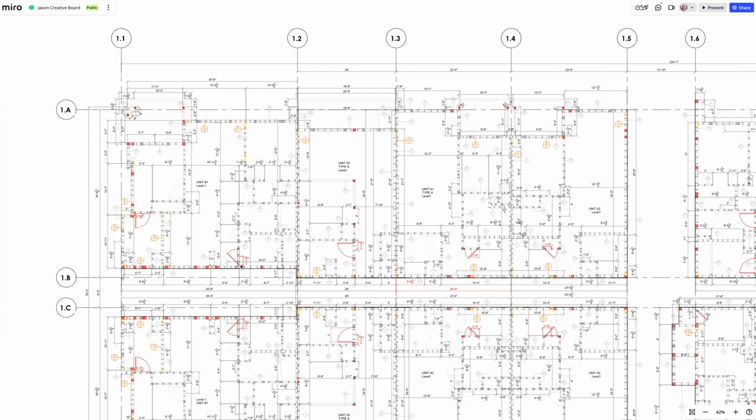And the reason this lift drawing was so important is because we can't QC the edge of slab for these buildings, and we can't QC the bolt locations, and we can't QC the hold down locations if we don't know where they are exactly. So they put together this lift drawing. Probably, I'd say about 45 key items came out by way of, we didn't write RFIs because we were in design, but 45 items that would have otherwise been an RFI were vetted in this process.